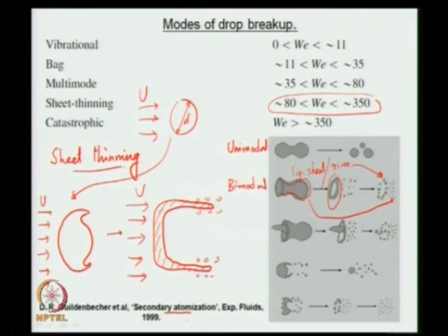This is more like our high Weber number diesel or jet atomizer, and so I create this thin elongated liquid sheet, which breaks up into finer drops, which are shown here, and a few large drops from the breakup of this disc like structure.